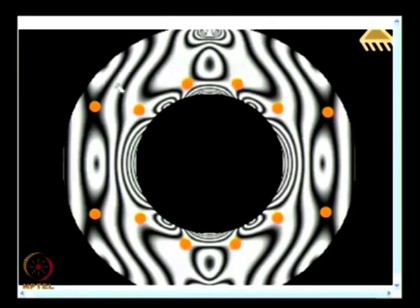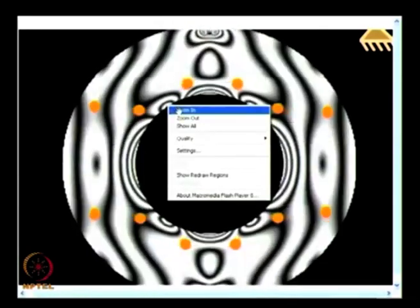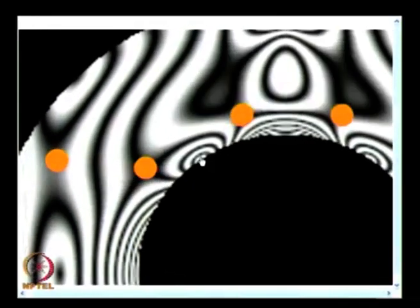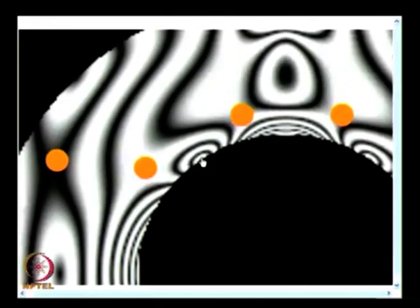And in a similar fashion you also have 0th fringe order on the inner boundary. It is difficult to observe. If you look here, as the load is increased, the density of the fringes increases, and this is again a 0th fringe order. We will verify this by a property of the isoclinic fringe field.